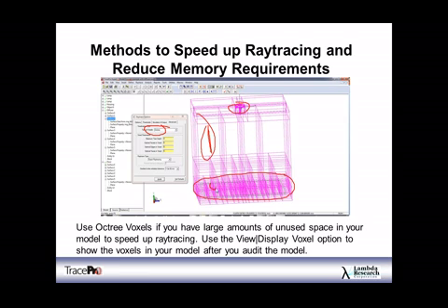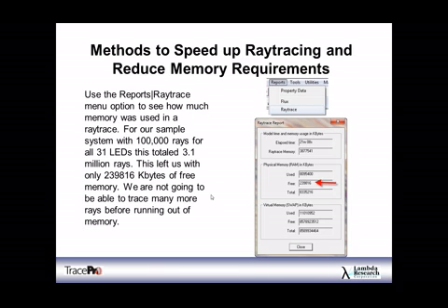And it's going to get sped up in this area because I have fewer surfaces in the voxels, because they're more concentrated around my surfaces. So try this for yourself sometimes. Try the elliptical reflector example. Ray trace it using regular uniform voxels and Octree, and you'll see the Octree is much, much faster just for this reason. So if you want to speed up ray tracing and reduce memory requirements, there's another thing that'll help you,